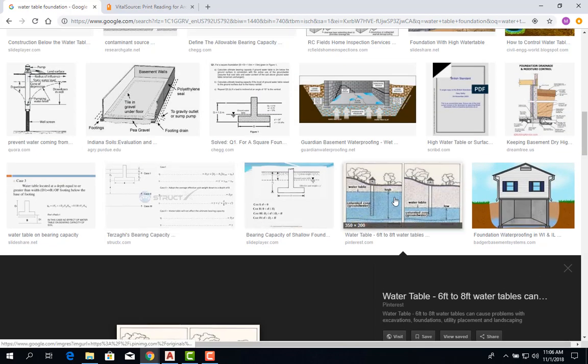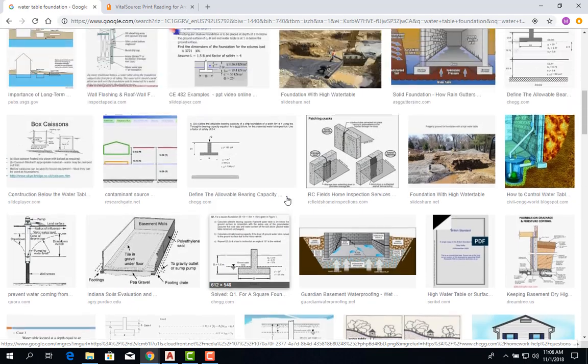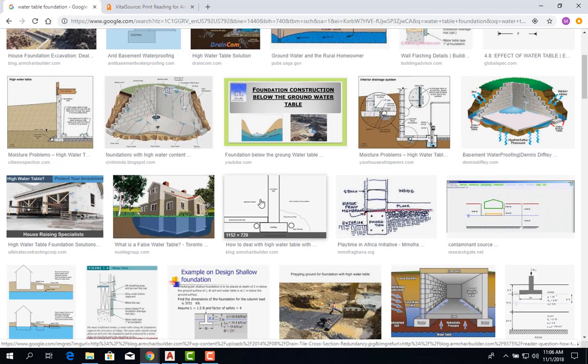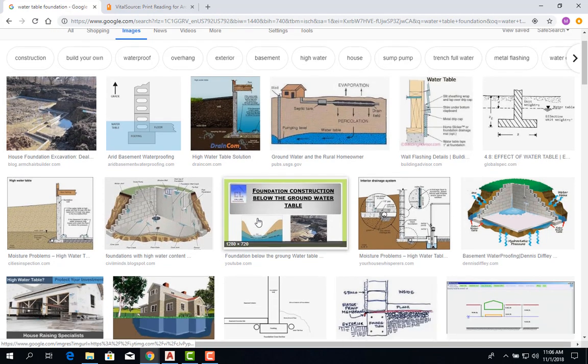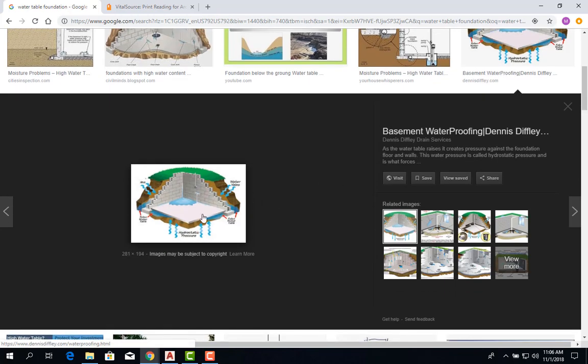And by water, of course, we don't mean just a stream of water. It's water running through tiny rivers, you could call them, or veins running underneath the ground. So you need to find that out first, because you don't want to have issues with water content on your foundation. Now, what might happen? If the water table is too close, it might weaken your foundation. You might have water coming in from the bottom, causing damage, or seeping into the side and causing damage. You don't want to have that, okay?